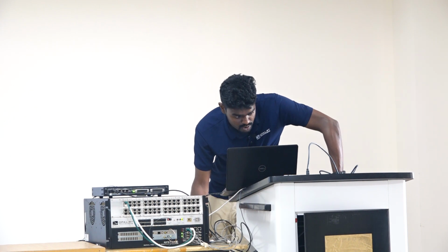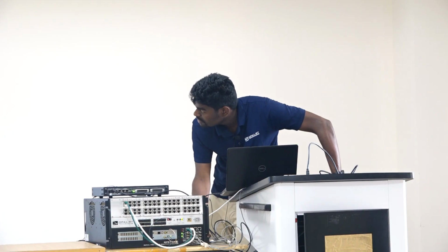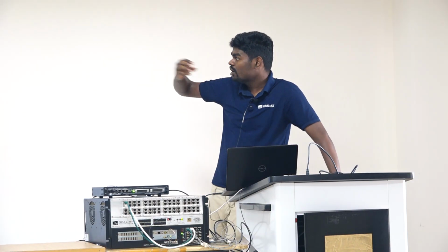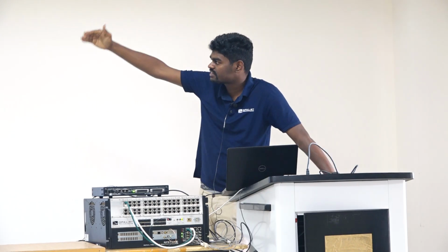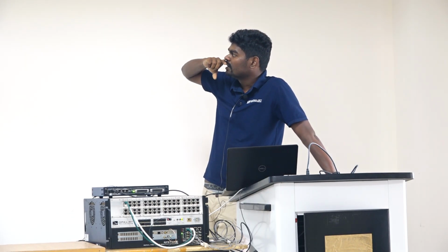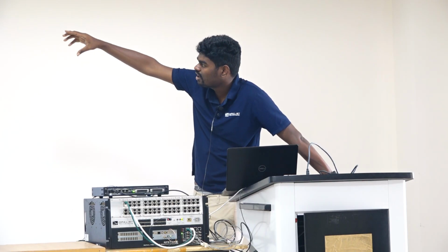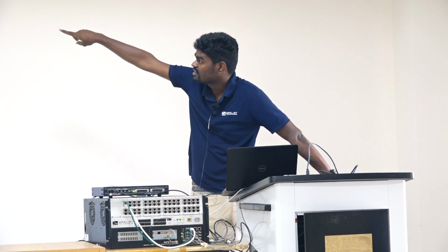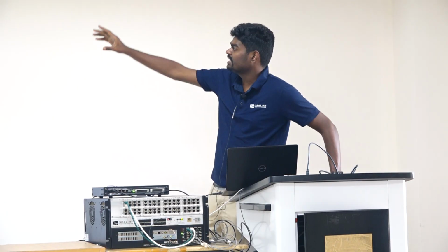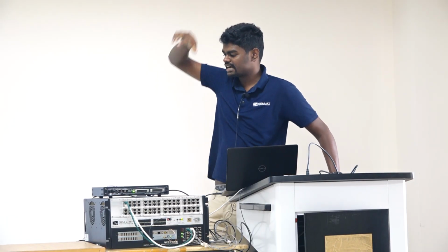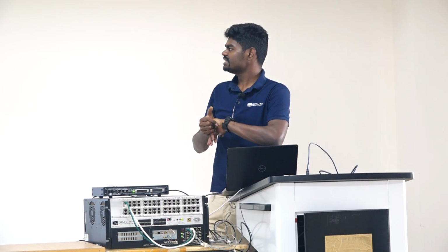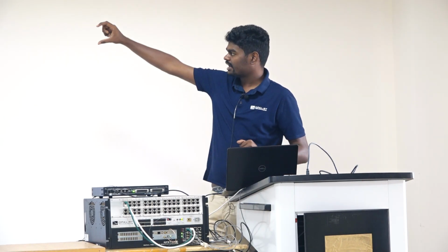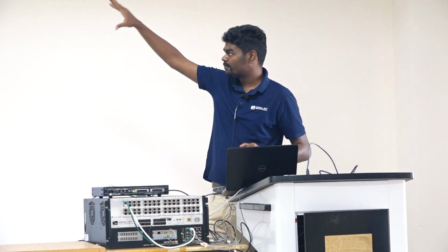Yeah, so here the controller is loaded. I'll just run it. Here I have added the control variables in CCS. All the analog inputs which I am reading, I have added here. Now you can see all those variables are reading a unit sine wave. If you see the value in this section, it is varying from -1 to +1, because currently, in order to test whether the analog inputs are working properly or not, I am just forcing a sine wave to see if it works. So currently you are reading the forced sine waves.